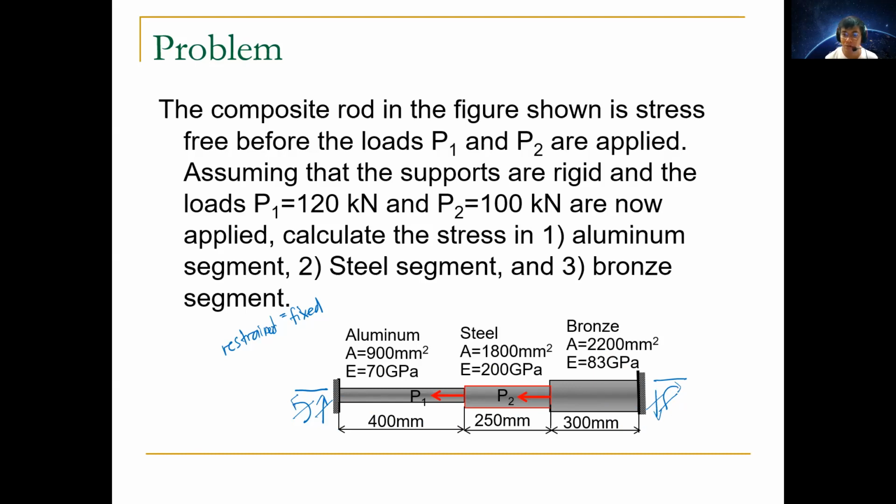But for the horizontal component, since we have an extra added force P1 and then P2, we can say that the reaction forces at both ends might be different compared with the vertical and the moment, which is just, let's say, of equal value because they cancel each other out.